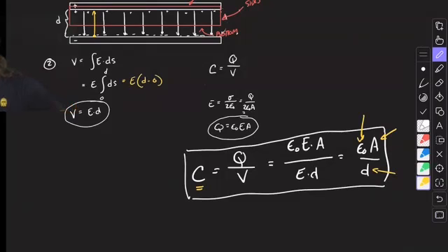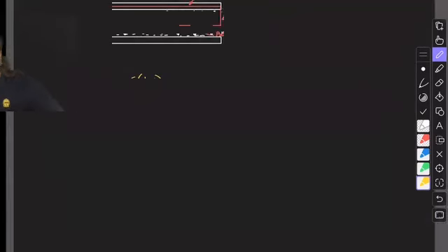So in general, we have limits to how big we can make capacitors in terms of their area and their separation distance. We can only get them so close. We can only make the plates so big. We want our phones nice and small, stuff like that. So what we tend to do is manipulate the space. We don't use a vacuum. We put something between the plates that enhances the electric field. And we call that a dielectric.